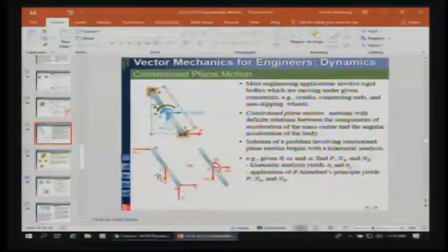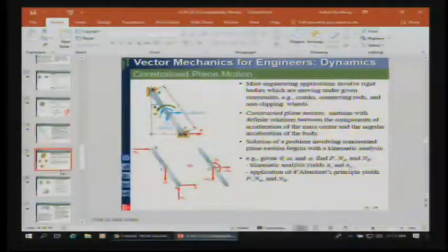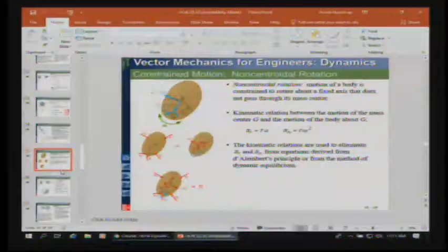So if you have a rod like this, you can think about the forces acting upon it as being the normal forces at the points of contact, the pull that's occurring here, and the weight acting from the mass center or the center of gravity, and then considering that m a bar and a rotation. So in this equation, we're considering m a_x and m a_y, in other words, the translational x and y components of the acceleration of the mass center, and a rotation. So you can see that there's a lot of stuff, and so using constraints, we can eliminate just a whole bunch of that.